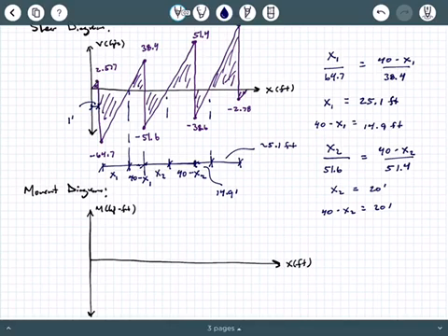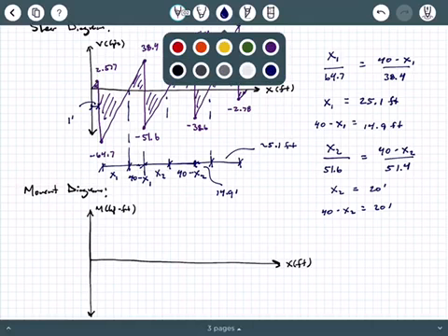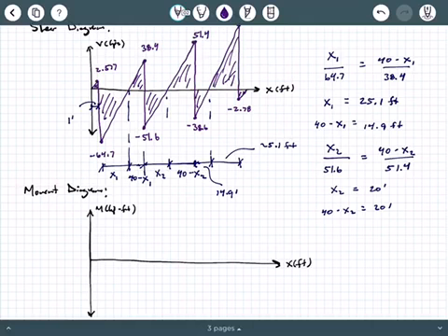So now let's get the moment diagram. Be very careful with your positive and negative areas. I'm going to start with this little bitty triangle on the left. So 1/2 base times height, 1/2 times 2.577 times 1 foot gets me a positive 1.29. Okay, so I'm going to come up right here, and that's an increasing linear function on the shear diagram, even though it's very small. So that means it's going to be a concave up quadratic segment.